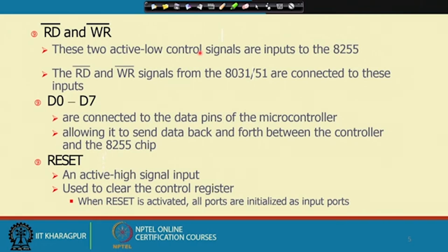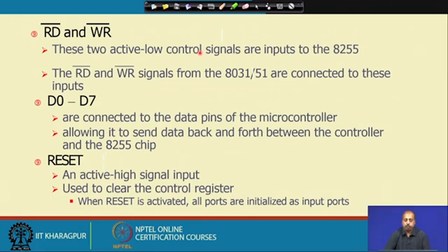Then we have got this reset. Reset is an active high signal. This is used to clear the control register. So, all ports will get initialized as input ports. This is the default configuration. When you reset the 8255 chip, all ports are configured as input ports.